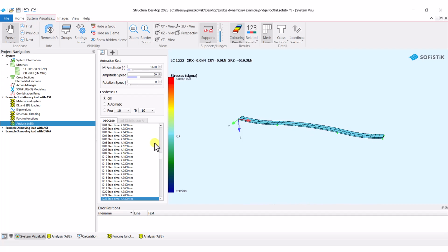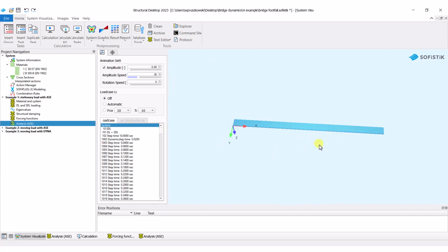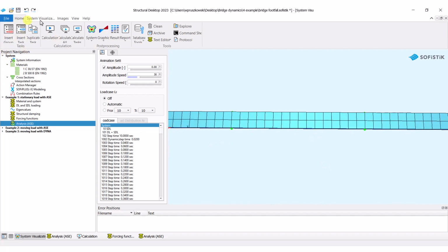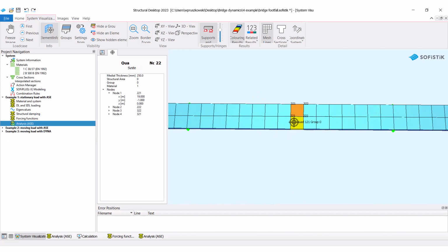And right around the 5 seconds mark, we see the maximum deformation and the system slowly settling, where we can observe the effects of damping acting on it. The structure's behavior over time looks good in the animator, but let's try to draw a plot of vertical deformation of one selected node, preferably in the midspan, over time, and let's confirm what we see in the animator. Let's select one node. In order to do so, we can select one quad in the middle, and let's say we will investigate node number 221.